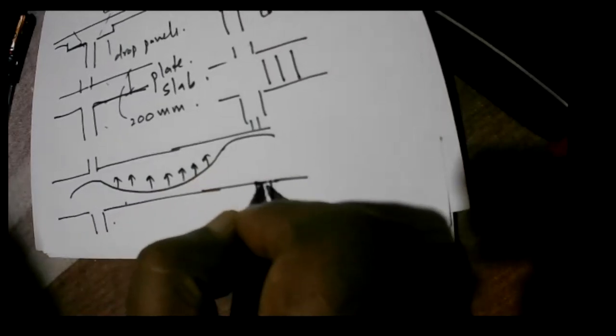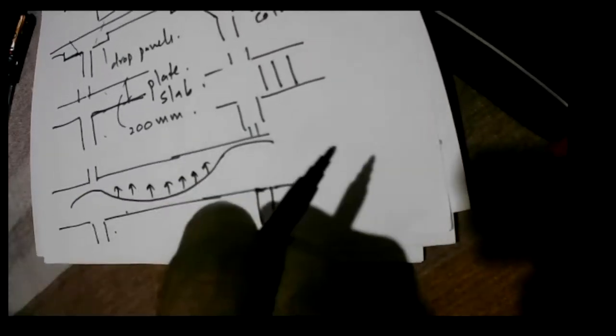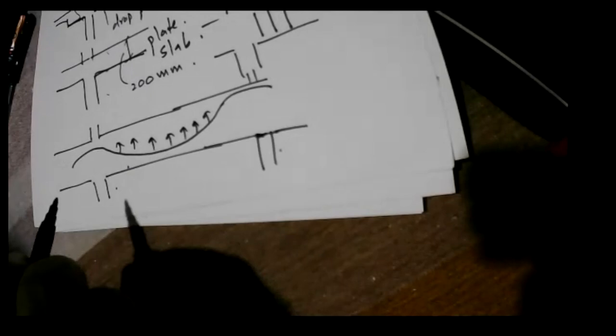In addition to that, you can also consider having a situation like this where we run pre-stressed tendons like this, and by having pre-stress we can lift the slab up and transfer some of these loads onto the column region. So this will be even more efficient, and these days this is gaining popularity due to the need for less reinforcement, because most of these loads are now transferred onto the column strips.